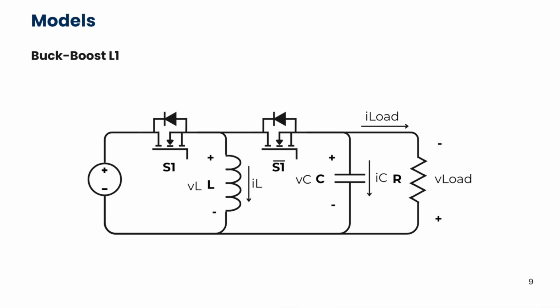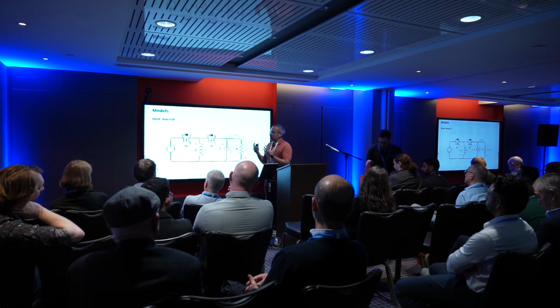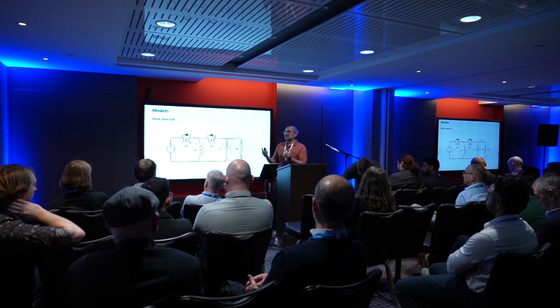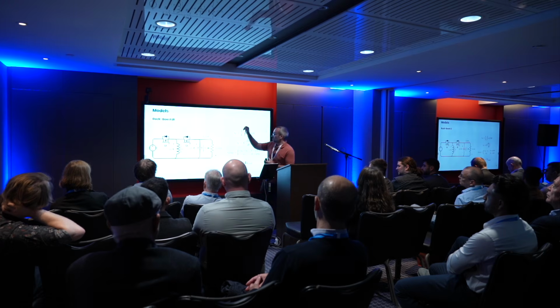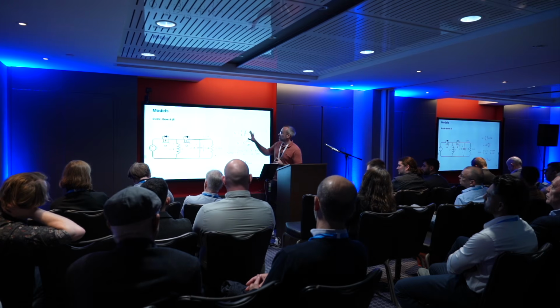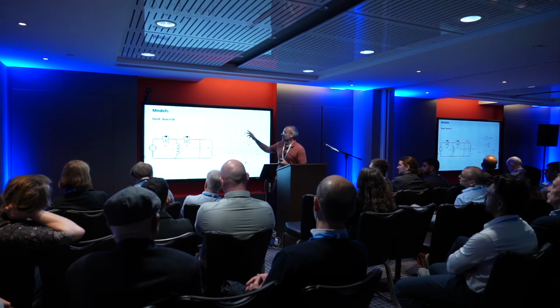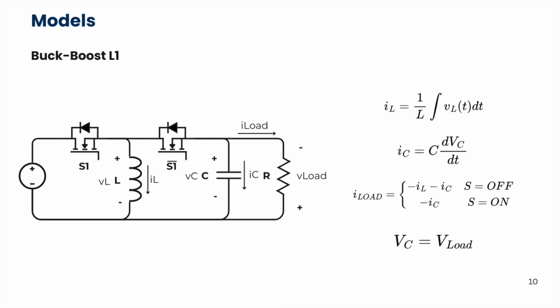In order to obtain the model of this circuit, and essentially of any circuit, we're going to need to know the mathematical equation that describes the behavior of that circuit. In this case, there are two elements that can be a little bit complex, such as the inductor and the capacitor, because they have what is called a state. The equation that represents the behavior of the inductor is this integral you have here. The inductor is, in this case, a current controlled voltage source, which is represented by the integral.